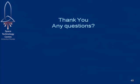Let me just finish your question. The issue arises if we're in the middle of sending a broadcast code and then an error occurs on the link. Then we take 5 microseconds to recover from that. So now we've immediately introduced 5 microseconds of jitter in our time distribution, which is really bad.